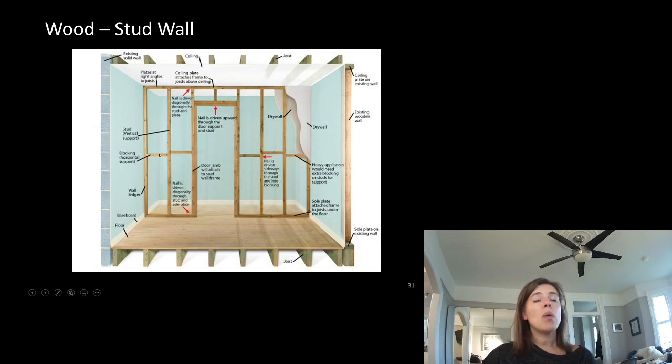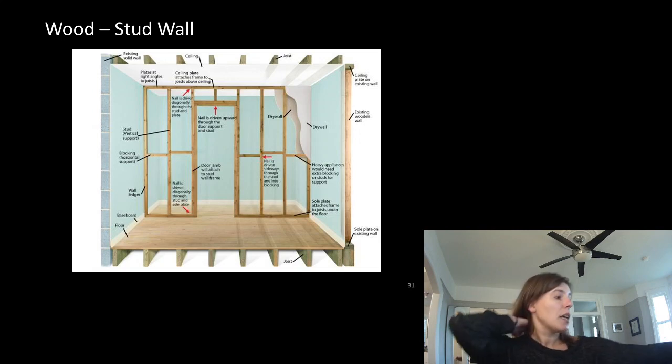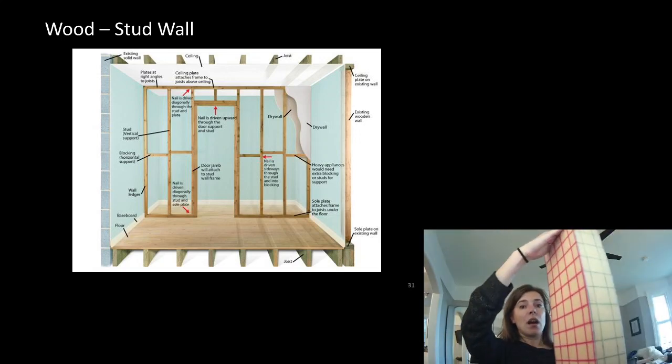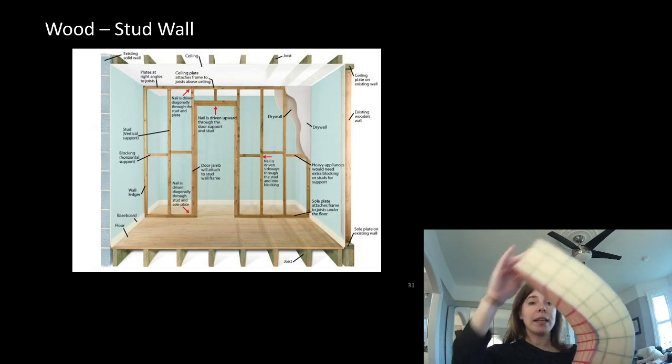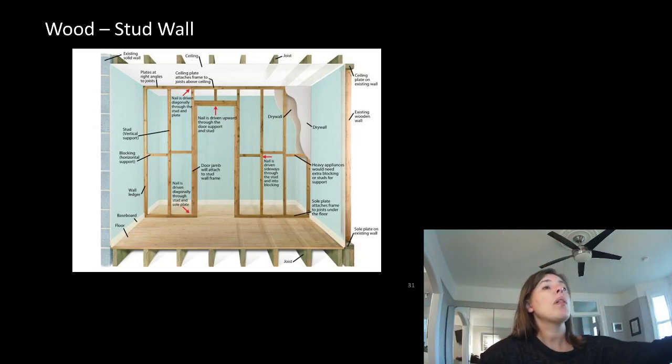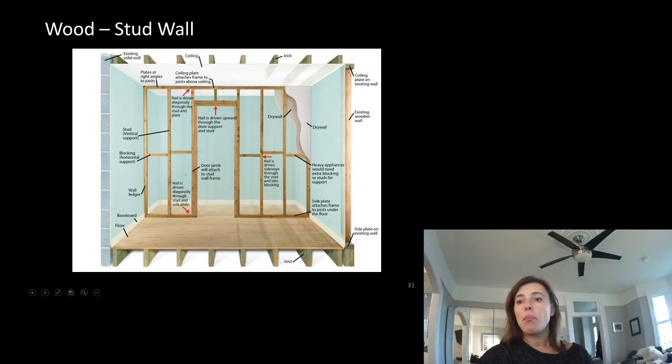And the same way we did with our floor joists, to prevent our studs from buckling in the weak axes, we'll often put blocking in between the elements. It needs to be somewhere around the middle, and they make it so that it's easy to nail these things into each other so that your nails aren't hitting.